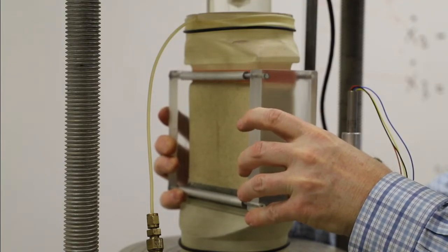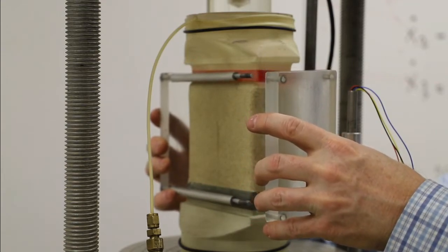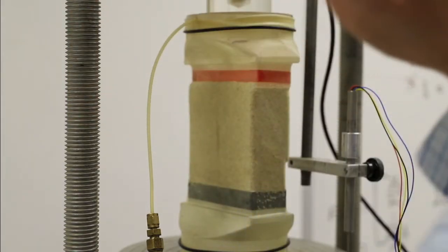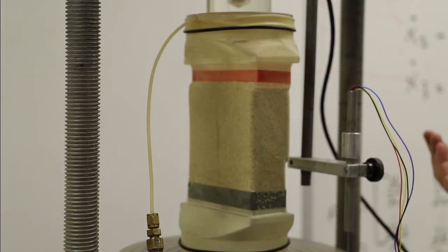So we read a value at the beginning and it holds throughout the test. So it's a constant. Sigma 3 is a constant. Well, sigma 3 total is atmospheric pressure pushing on the outside, right? But sigma 3 prime is the vacuum as a minus pore pressure, right? Negative pressure on the inside leads to positive effective stress.